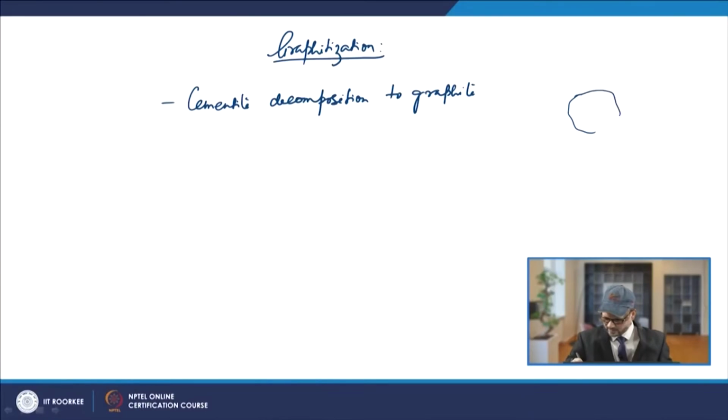Many times we add aluminum to the steel, and carbon steels as well as carbon and half molybdenum steels are very much susceptible to this defect known as graphitization. On the grains you have the grain boundary, so there will be grain boundary carbides formed along the grain boundaries.